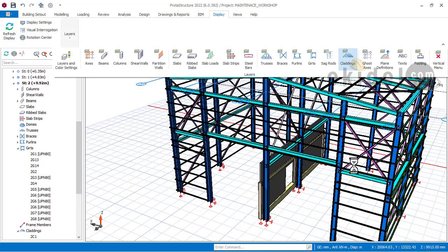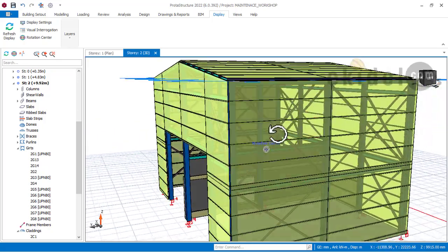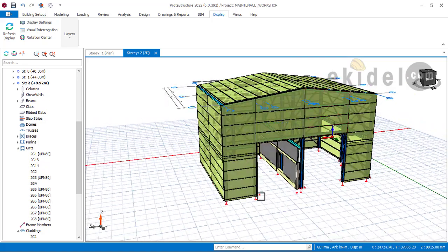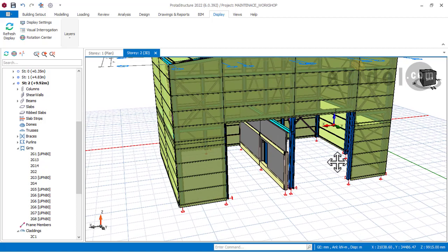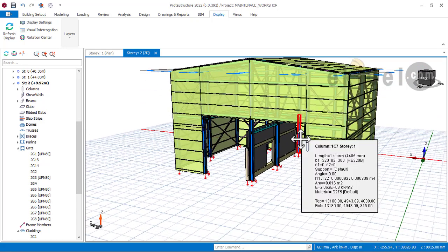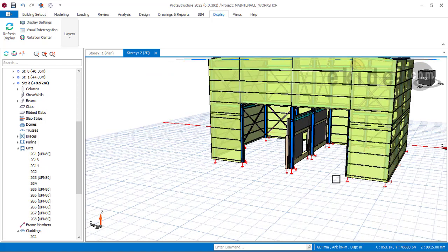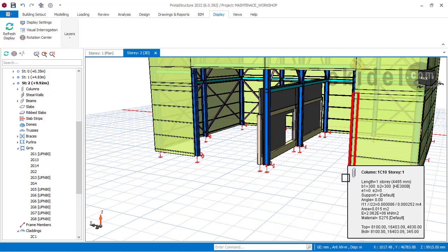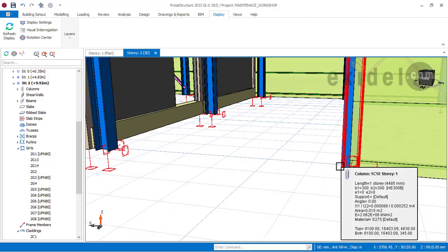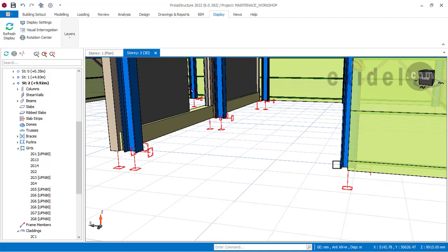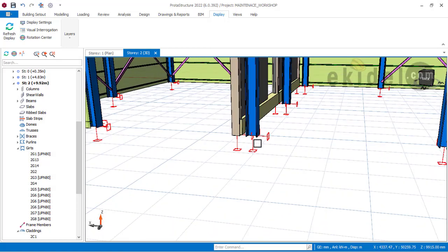Okay, so you can now see what we have done so far, how we created this steel warehouse up to this very step. On the next part of this maintenance workshop steel building design, I'll be showing you how to create our concrete pedestal. The environment where this workshop is going to be built has what they call water logging. Because of that issue, we are going to create a very big pedestal of at least 1 meter height, so that it can protect this steel from rusting, because the level of water when there is water logging on the site is 400. So because of that, we added an additional 600 to the height of our cladding to be able to protect these steel members, both the bolt and the base plate, from rusting.